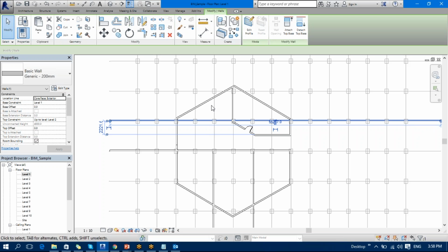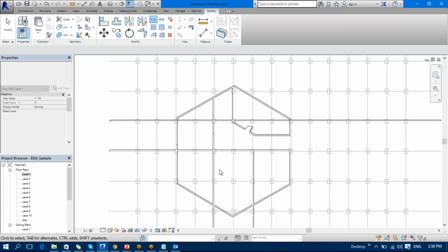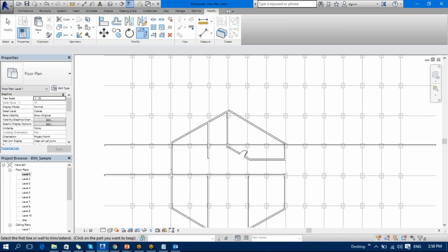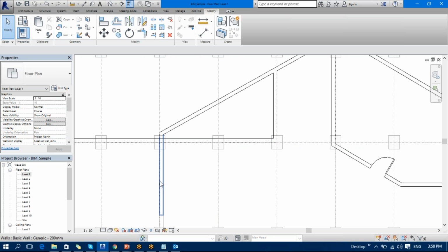So what I'll do is first I'll extend this wall. I'll say TRS, select this, select part, then I'm going to split from here because ultimately I don't want any wall here. So I'll say TR here to here, and then TR here to here. Then I don't want this wall to be separated.